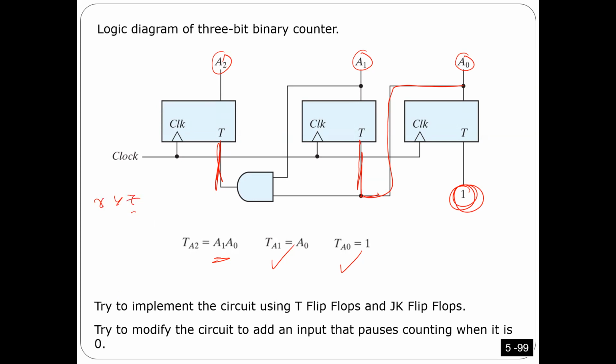If you look at the first one here, 0, 0, this one should have 0, 1, 0, 1, 0, 1, 0, 1. Is that right? So you have to toggle every clock. So if you want to make numbers, this one has to toggle every time. The second one here should be 2 zeros, 2 ones. As you will see right now, because of this one here, it is going to make it toggle for 2 clocks. You will see right now.